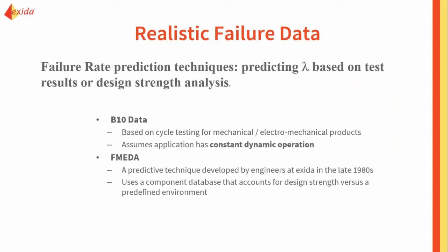The other way of looking at failure rates is predicting failure rates. Just like with estimating failure rates, there are pros and cons with both of these methods. A pro for both predictive methods is that you don't have to have that historical data to do these. This is especially good with software and electronics that seem to be changing more often than maybe a simple ball valve would. So the predictive technique you can do on new designs or old designs.